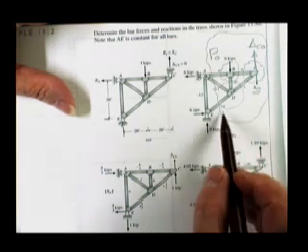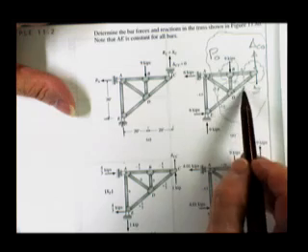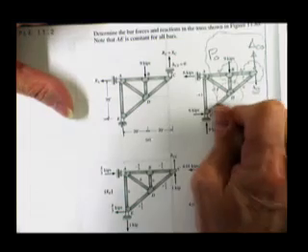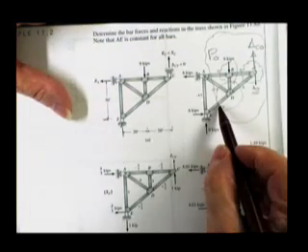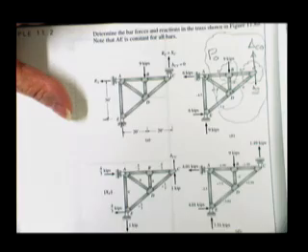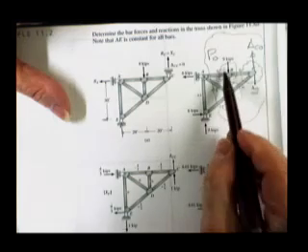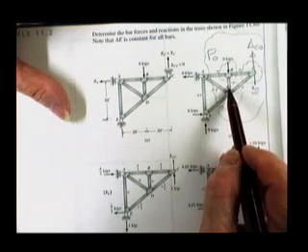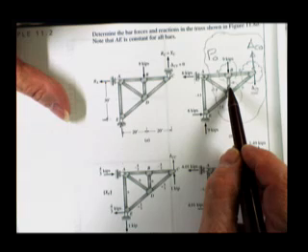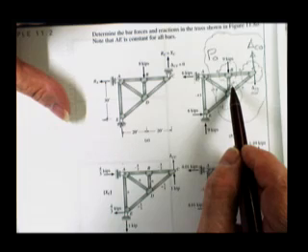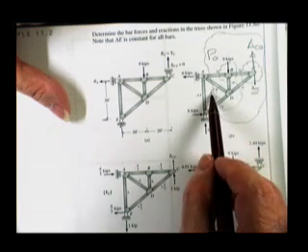So here's the final answer for all the forces in the members due to the real loads applied: 0, 0, 9, 0, 7.5, minus 7.5, minus 4.5. And if you're wondering what his sign convention is, if this is 9 down, this is 9 up. 9 up must mean there's something pushing up on the joint, and that must be a compressive force. So he must be using compression as a minus and tension as a plus.